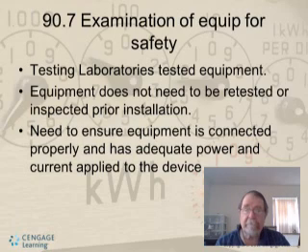That is, manufacturer's specs may specify that. If there are none, then you need to figure out current draw of the device and do some calculations to figure out the best way to connect it. But most manufacturers send the circuit type, the amperage, whether it's 3-phase, or 220, 240.